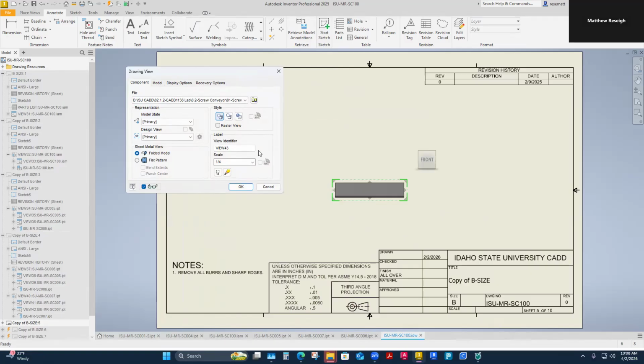Which one is a jacked up one? That's okay, I'll still place it and hope to fix it. When I go to fix that flat pattern, I may have to delete that flat pattern a few times. And if you delete flat patterns, then you lose them on the sheets where you've placed them. So if I ever delete a flat pattern that's been attached to a sheet, I pretty much have to go back to that sheet and re-put the flat pattern on. Sometimes you have to do that a few times. Or if you think about it ahead of time, you might say, I'm not ready to put that on a sheet yet because my flat pattern is still jacked up. But here I'll put it on there and we'll go through that process.